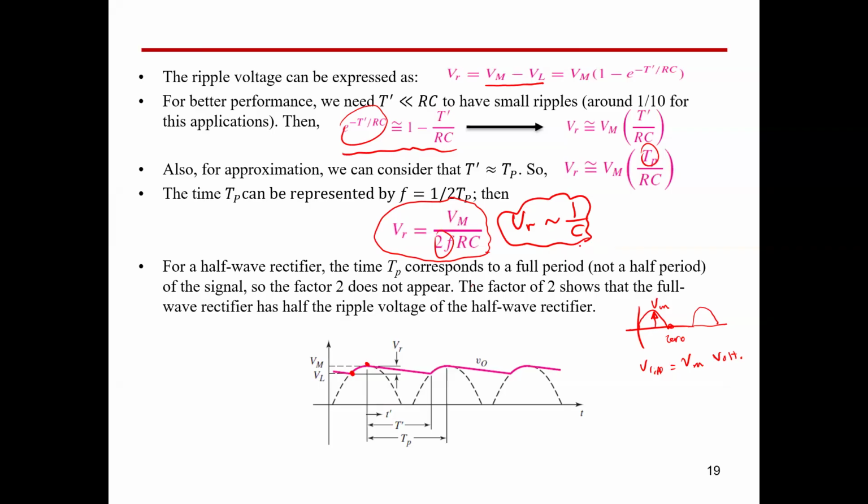So we will see together now some numerical examples. How can we size a capacitor in order to limit the ripples to a certain amount? You cannot have zero ripples. The ideal is having zero ripples, but we mentioned before, ideal is something impossible. We don't have anything ideal in our life. So you have to have some ripples. Also, cost-wise, you will not increase the capacitance very much because the cost will be very high. So you have a cost limitation as well. So we will see together now, guys, how we can size this capacitor.